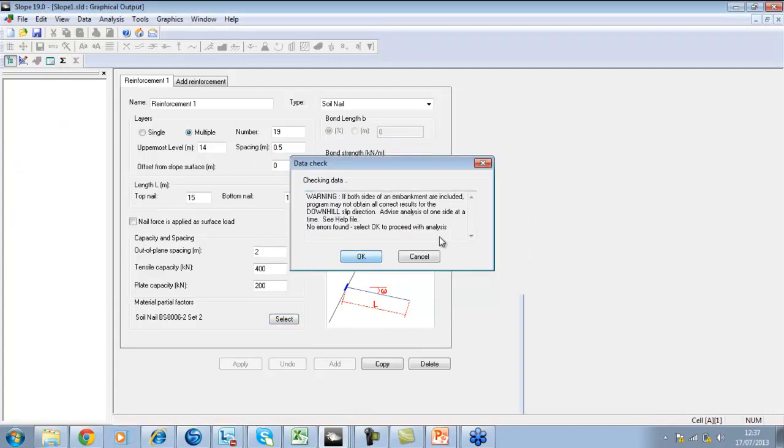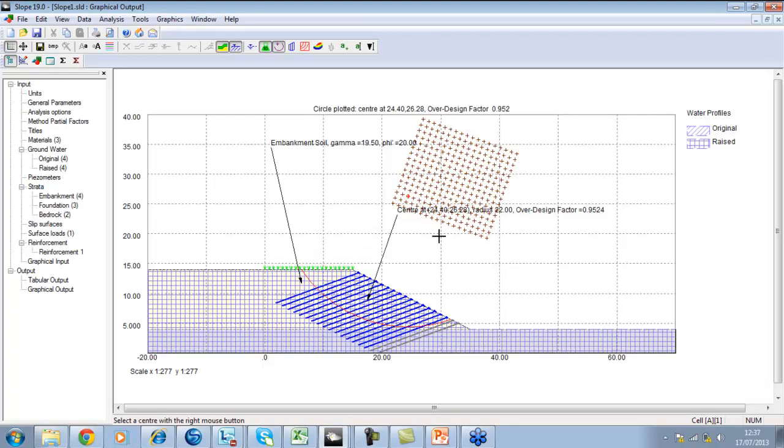So the reason I'm going through these different iterations is, as you can see, we're getting something much more acceptable now for Eurocode 7 Design Approach 2. The reason I'm going through this many iterations is so that you can see what's happening, and how this design is working, and how the designer themselves would go through and run iterations between different analyses. Okay, so I think that's pretty much our run through.